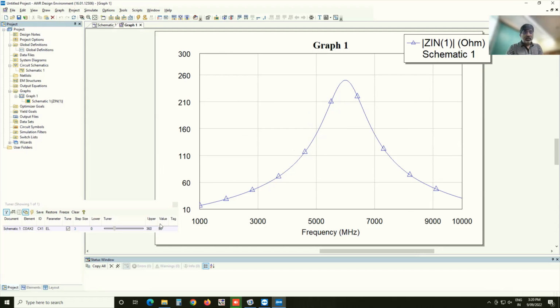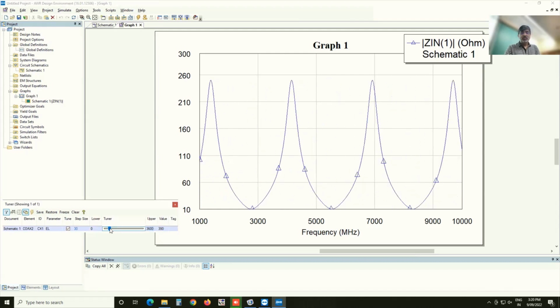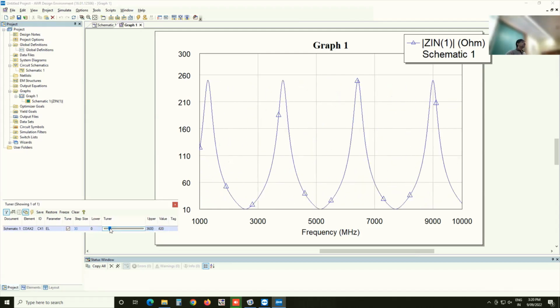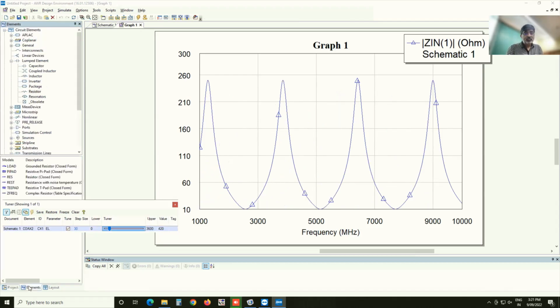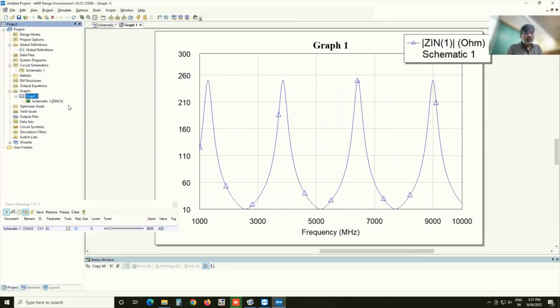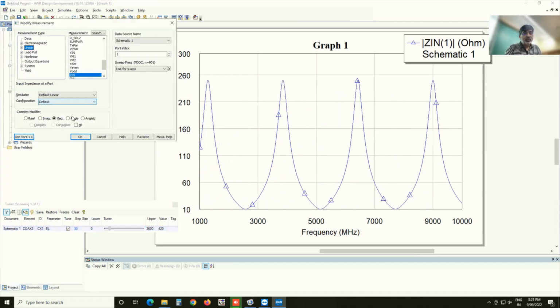Okay. Now, if I allow this electrical length to become larger, then you see this whole pattern just repeats. It's periodic in this thing. So when you connect a transmission line of a particular length to a device, to some load, the effective impedance can vary wildly from its original value all the way to some other values. Now, let's actually look at these. Instead of looking at the magnitude, we will look at the real and imaginary parts.